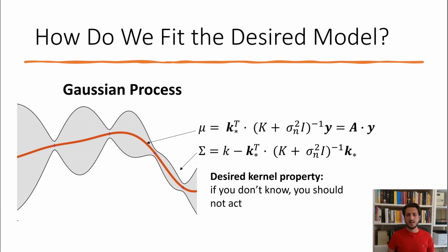And the squared exponential kernel of a Gaussian process allows the vanishing of the prediction. And this vanishing brings the robot to have zero delta, so not moving anywhere, and also to have the drop of the stiffness that results in a compliance of the manipulator.